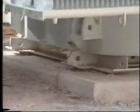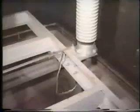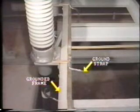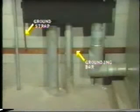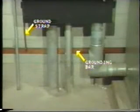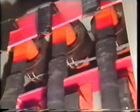The external metallic frame of switchgear, transformers, substation structure, motors, relay panels, and so on are all solidly connected to the ground mat. You are well aware from your trips to substations that the grounding straps are always of considerable current carrying capacity to provide an easy path for flow of stray currents or fault currents to ground. The potential of all framework throughout the area is at the same ground potential, so providing safety for personnel working in and around the equipment.